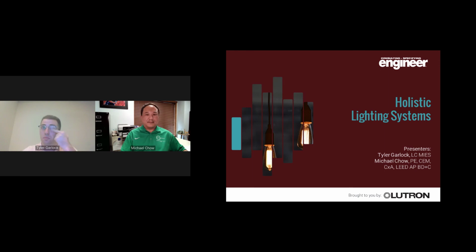Who on the design team should sign and be listed on the CommCheck lighting compliance form? Oh, that's a great question. CommCheck, which stands for commercial check, is a form available on energycodes.gov. There's an online version and a version that you can download. Once you pick the energy code, it populates a form that you fill out, and then it produces a compliance report.